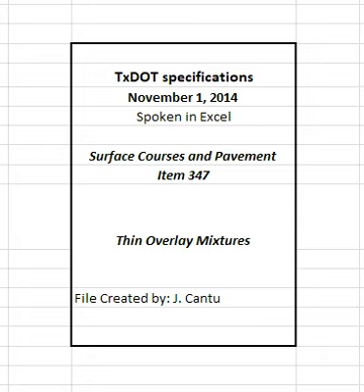4.7.3 Laydown operations. 4.7.3.1 Thermal profile. Use a handheld thermal camera or a thermal imaging system to obtain a continuous thermal profile in accordance with Tex-244-F. 4.7.3.1.1 Thermal segregation.